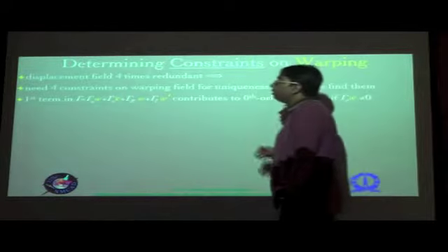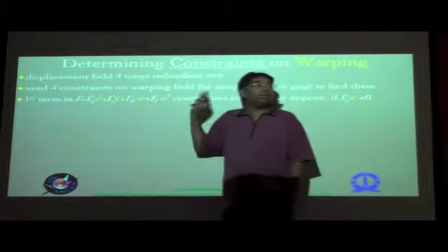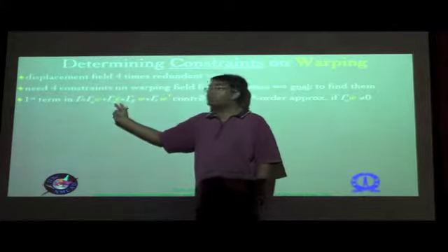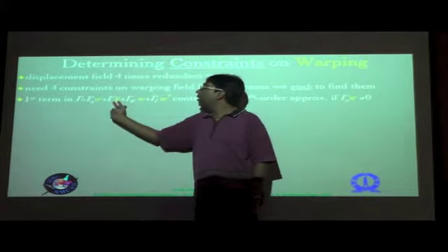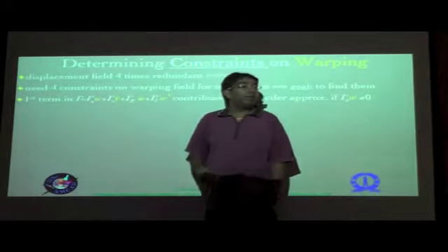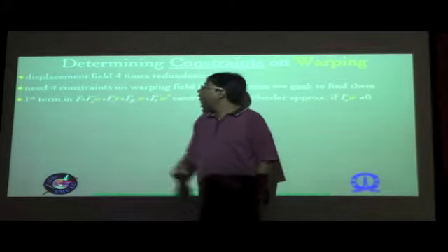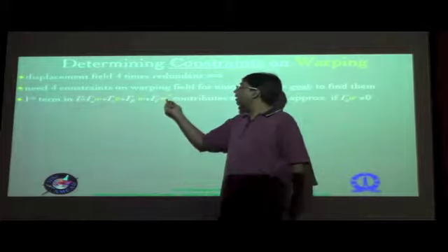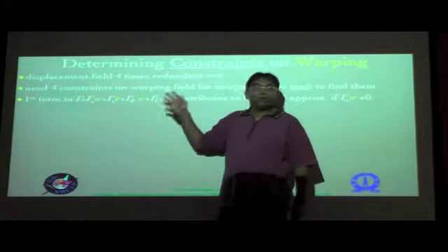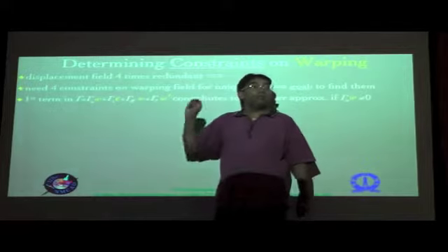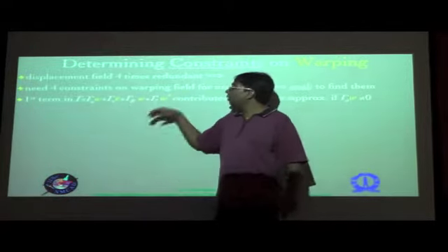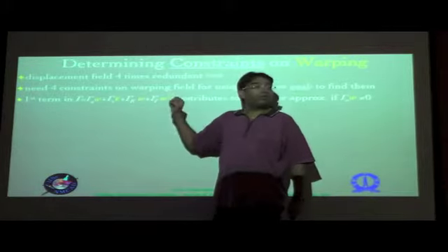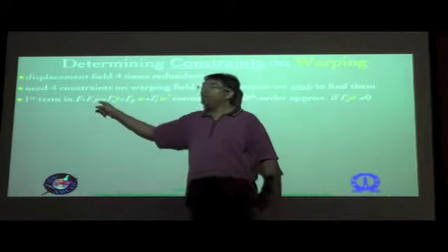One way of determining it is to just look at the expression we had for the strain in the previous slide, which is basically this. I've just interchanged the first 2 terms, put the gamma epsilon alpha epsilon bar over here and put the gamma A W over there, because our focus is now going to be on this particular term. Amongst all the three terms which are contributing to warping, one is basically a higher order contribution because it involves a W prime, and one is something which is specific to beams which have initial twists and curvatures. So when you have a prismatic beam, for example, that will not occur at all. So the primary contribution for warping for all beams would basically be this particular term.